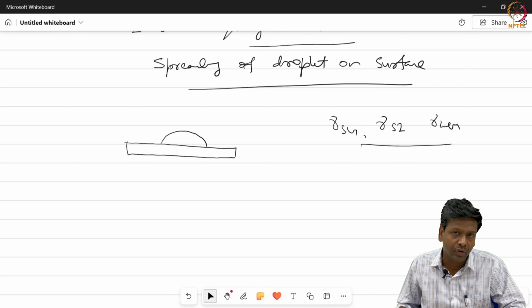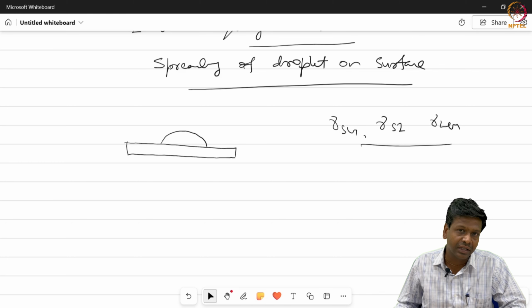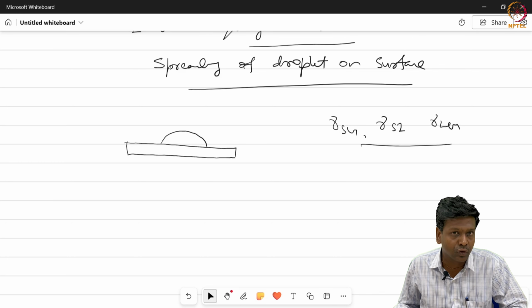On the other hand, let's say you want to make waterproof fabric. In this case, you want the surface to have more water repellent property. Usually it should exhibit a contact angle with water above 150 or 160 degrees, so the surface behaves as super hydrophobic.